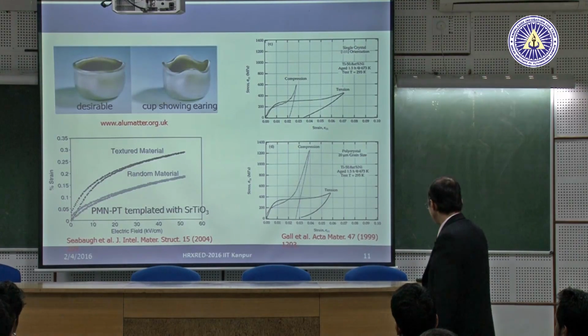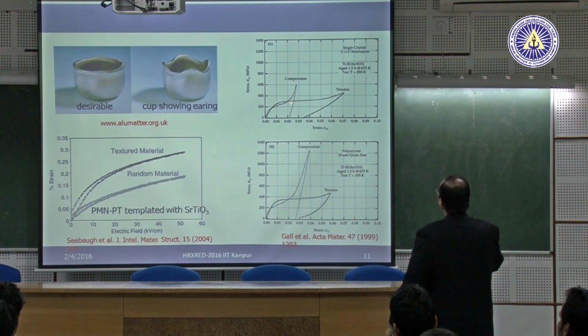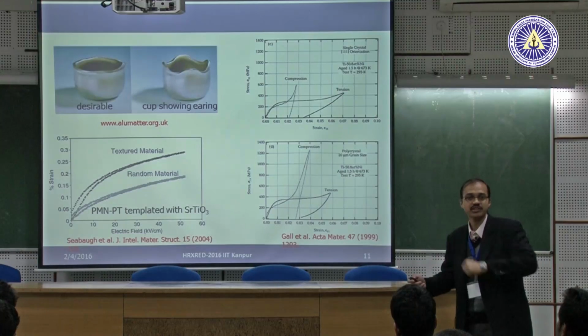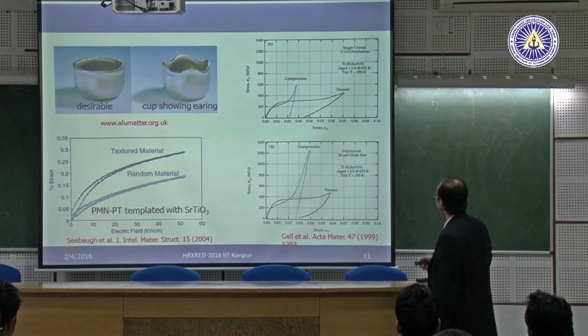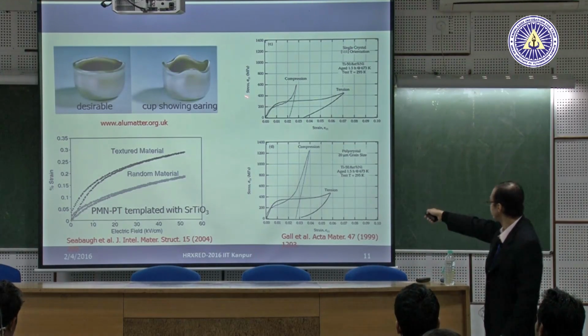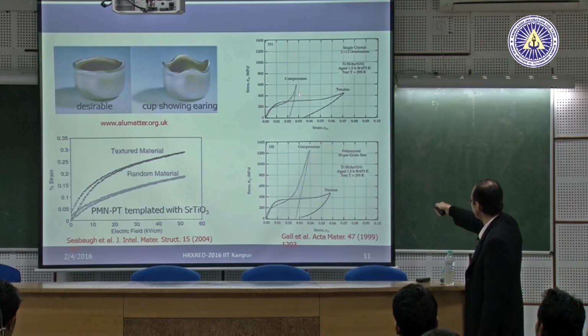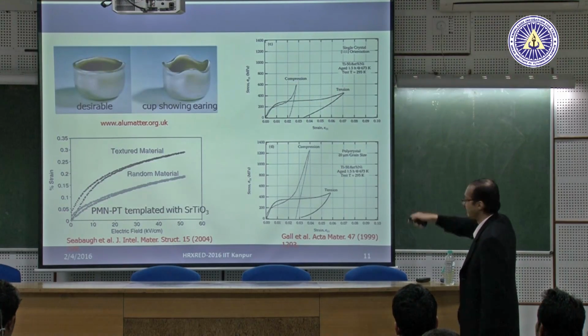Okay, so here I have shown you nano indentation data, which is as good as looking at a single crystal. So here it is, for single crystal. You see the 111 single crystal. You see how much anisotropy there is, right? Now you can see the difference in the shape as well as the peak that you are having.